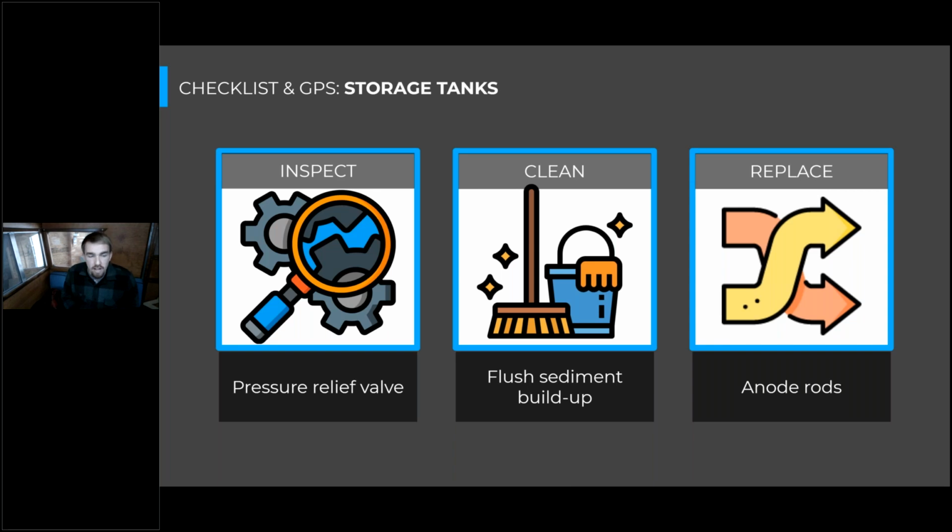Yeah, with VRFs, say, if we're talking about space heating, for example, there's a lot more. The condenser and the evaporator are usually split apart with a lot of refrigerant running between these two sections. So now you have two different pieces of equipment that you're maintaining, and they're in a slightly different application usually.